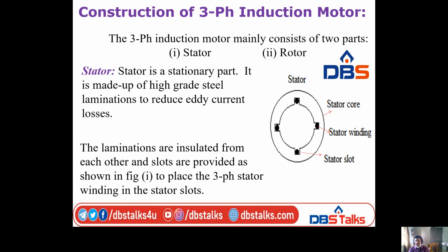The stator is a stationary part and it is made up of high grade steel laminations to reduce eddy current losses. The laminations are insulated from each other. Slots are provided as shown in figure 1.